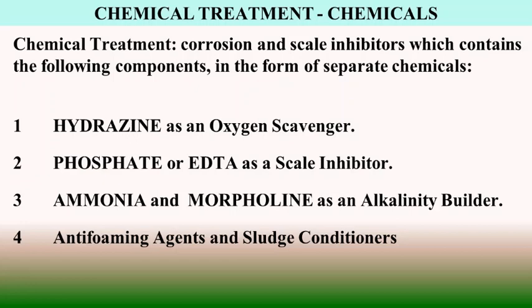There are various methods of internal treatment, like phosphate hydroxide, coordinated phosphate control, polyphosphate polymer based control, application of chelants, EDTA, and application of organic treatment like filming amine.